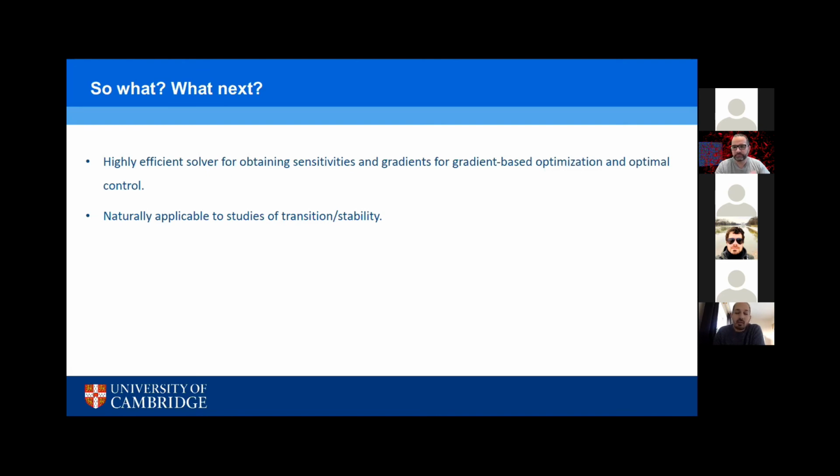So that is standard for the continuous adjoint. You just have to derive it. You have to go through the derivation. For the convective outflow, I believe you will get a Dirichlet condition for the pressure, which is not exactly compatible with how the pressure solver at the moment is in Xcompact3d.